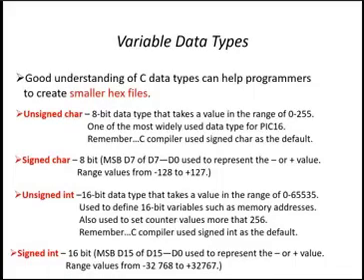Okay, starting from 0, and then this is the limit, the maximum value 255. This is decimal. This is 8 bit. So we have 8-bit. So unsigned char is reserved for 8-bit data. So if your data is in the range of 0 to 255, you can assign it to char. But if your data is larger than 255, maybe 300, 400, that one we will see later. Right now, if your data is in the range of 0 to 255, you can use unsigned char.